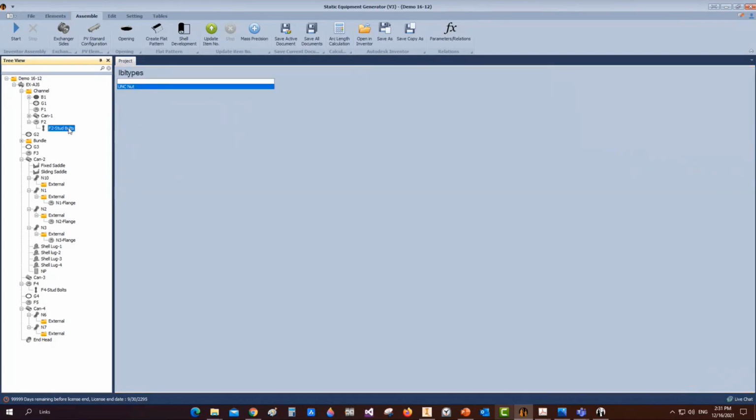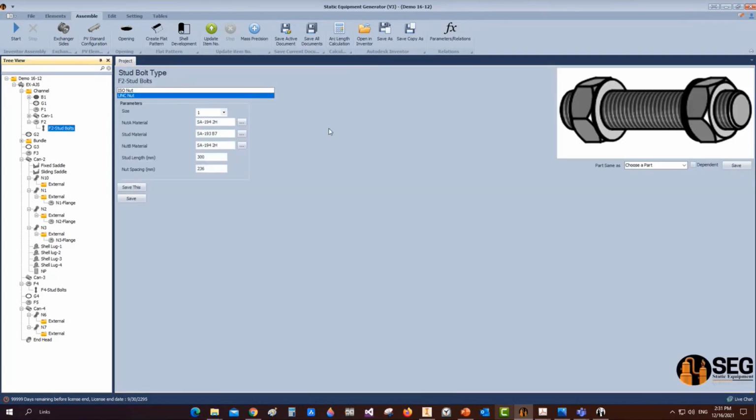Yeah, but this is the question they are asking. Okay, if you can figure it here. We use this UNC bolt or stud bolt. For the UNC bolt, we normally use till 1 inch. Above 1 inch, we used to follow UN8, means 8 thread minimum. That's the TEMA standard. No, that's the standard here or the database here for bolts.